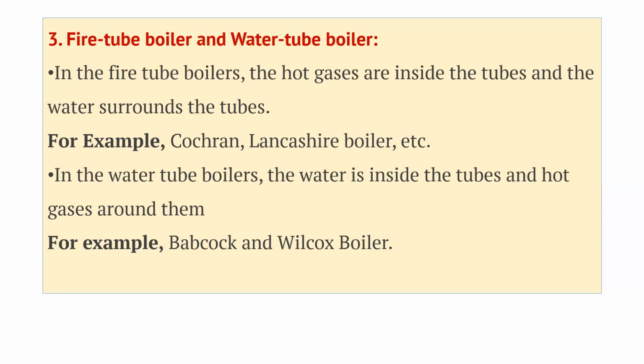Don't be confused about what is fire tube and what is water tube. Simply, the name itself has a dash; in the dash, you fill in your mind: fire in tube, water in tube. So fire tube means fire inside the tube. How will the fire be inside the tube? It will be hot gases. After burning the fuel, you pass the hot gases inside the tubes, and the tubes will be surrounded by water. So automatically there will be heat transfer, and the water will get heated.